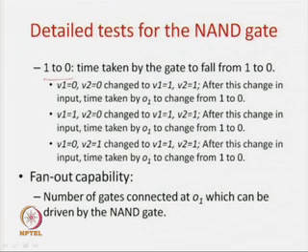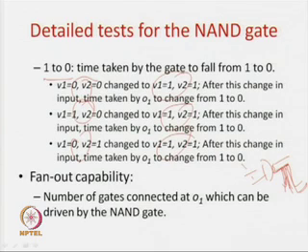Now, you also have to have a delay test from 1 to 0. We require this curve: how much time it requires for this delay, because initially it was 1 and now it is falling to 0. So, how do I get a 0 in the NAND gate? You know that the answer has to be 1 1, so all inputs will be 1 1, but from where can I reach a 0? If the inputs are both 0 0, the answer is 1, and likewise for the other two cases. So, from these 3 input cases, if I go to these output cases, I can get the fall from 1 to 0.